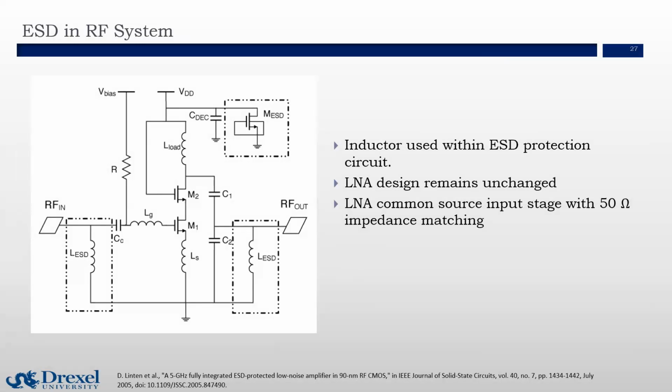In this example, we use an inductor embedded within the ESD protection circuits so that we can make the LNA design remain unchanged, and we just need to deal with the ESD protection device. And we assume an LNA common source input stage with a 50 ohm impedance matching.